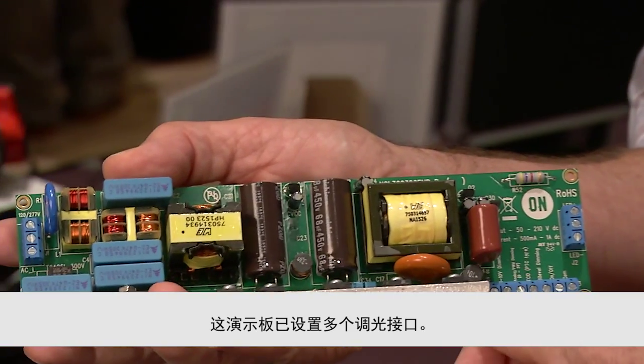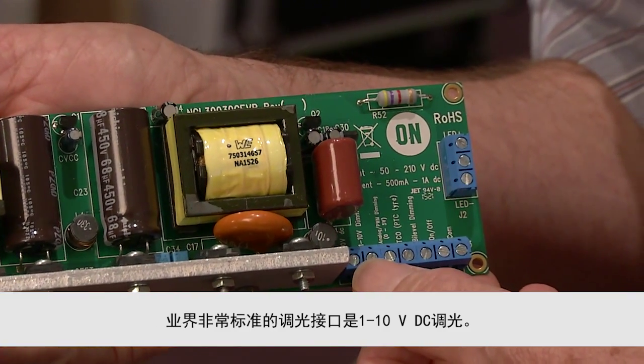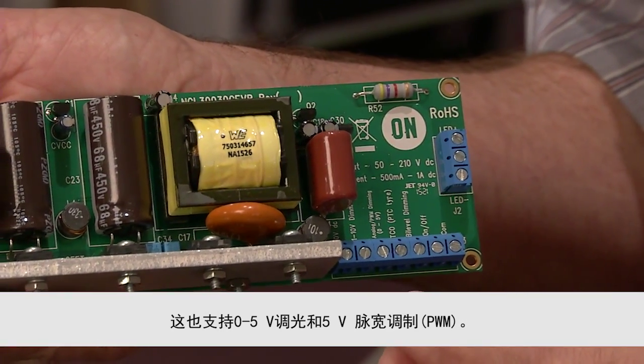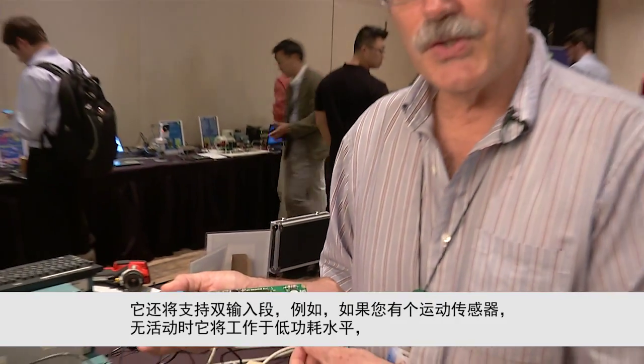The demo board has been set up with multiple interfaces for dimming. A very standard dimming interface in the industry is a 1 to 10 volt DC dimming. There's also 0 to 5 volt dimming supported, as well as 5 volt PWM. The PWM may be a 200 hertz waveform where you adjust the duty factor to adjust the brightness. It'll also support a 2-input stage. For example, if you had a motion sensor, it would operate at a low level when there is no activity, and whenever there's activity in the area, it would step up to a full brightness, therefore saving power whenever there aren't any occupants in the area.